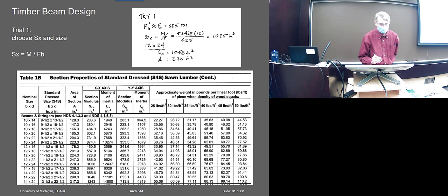Okay, so here we go. Calculate the section modulus. We got this, and it's neglecting the dead load, I guess, but okay, close enough. And the stress that we got there, we're not putting any factors on it, so first time through, we'll do it without the factors.